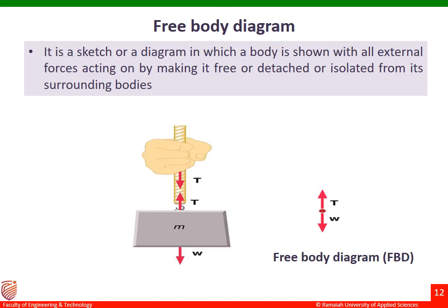In engineering mechanics, whenever we want to solve any problem, the very first step is to draw the free body diagram. Without drawing the free body diagram, it is very difficult to solve the problem. So always, the very first step is the free body diagram. That means you should always represent the forces acting on the body in the free body diagram. Once you draw it, you can easily write the equations and solve the problem. So the free body diagram is very important in the engineering mechanics course.